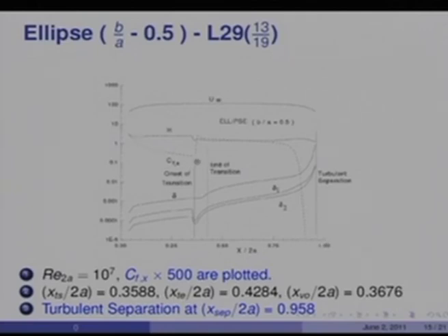So, you can see the skin friction behavior is quite different from that for a cylinder, but in both cases turbulent separation is encountered. Here a finite laminar transition length has been encountered, whereas in the flow over a cylinder we found no transitional length and the laminar separation was straight away taken as the start of the turbulent layer. The shape factor again is of the order of 2.5 in the laminar regime and then it decreases to around 1.3, 1.4 or so of that order.